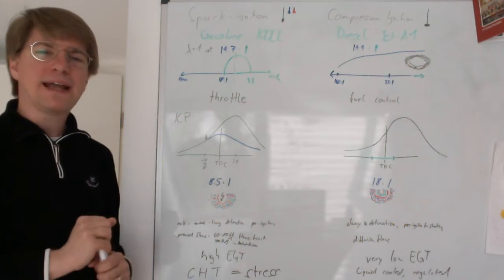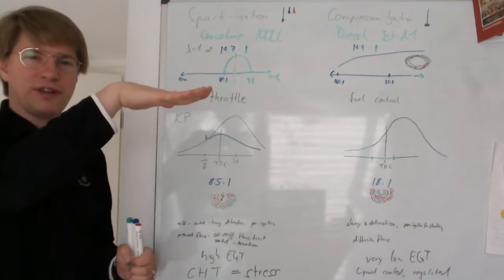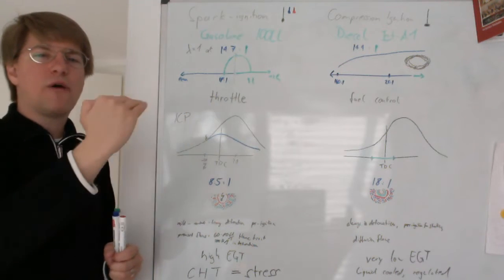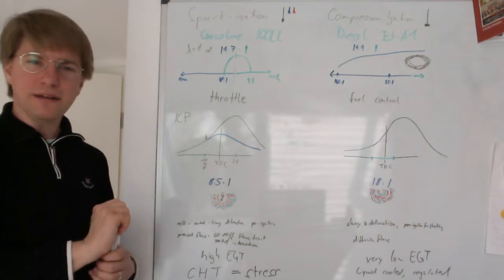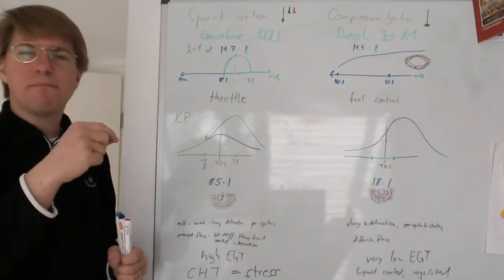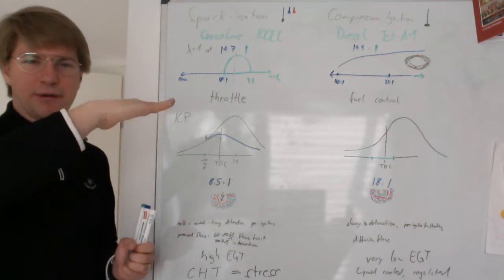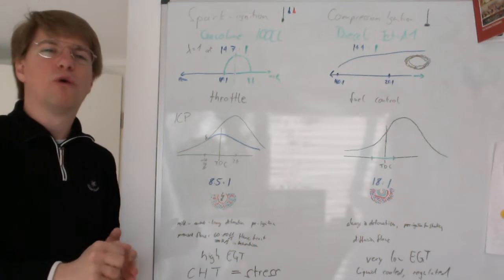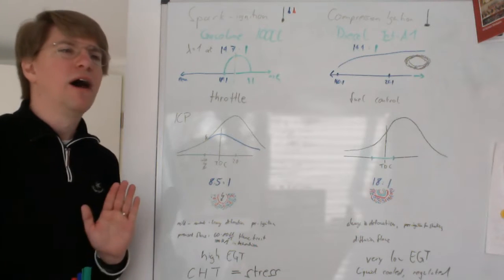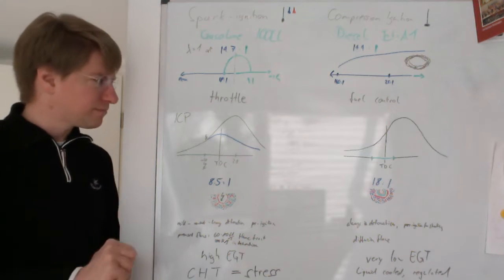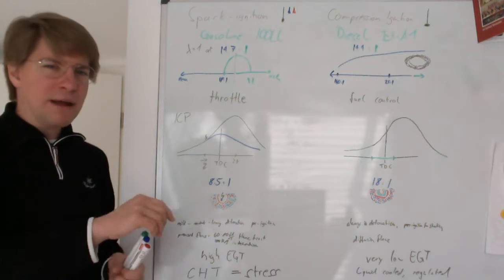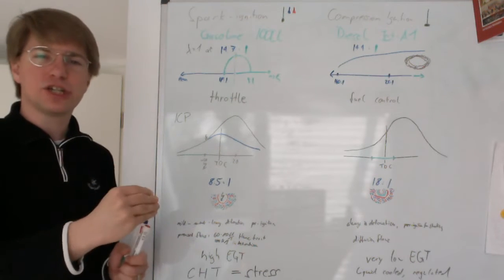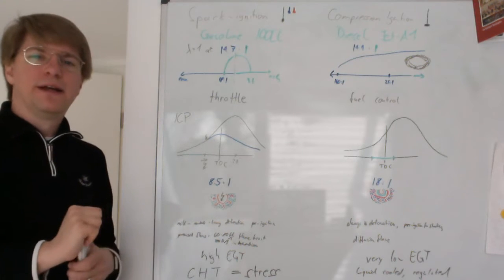With our black knob, we change the butterfly valve in the intake manifold, allowing more or less air in, and the amount of fuel that matches the amount of air we let in with the throttle valve is matched by either the carburetor, the pressure carburetor, or the fuel control system of the multi-point injection. So primary power control is by how much air we let into the engine, and then we match the fuel to it.